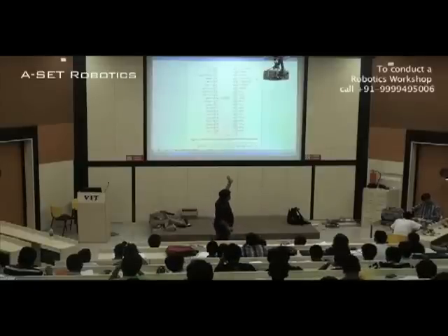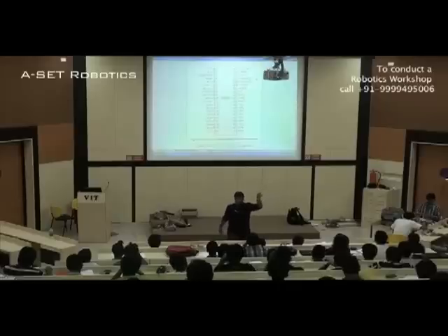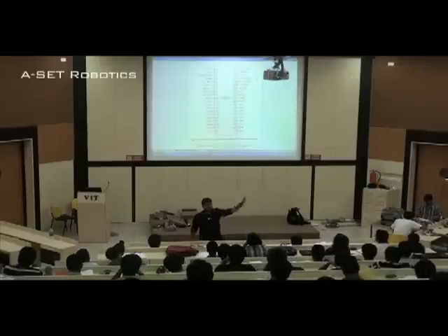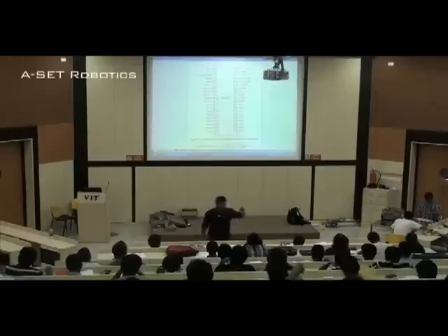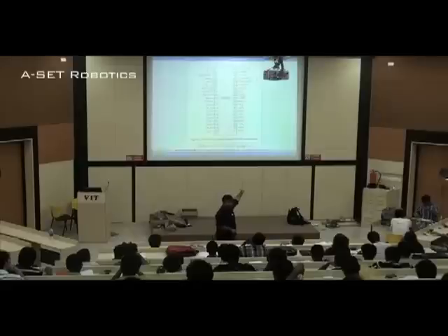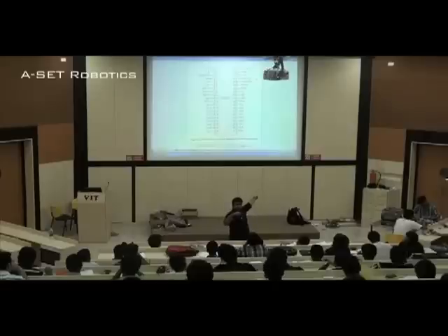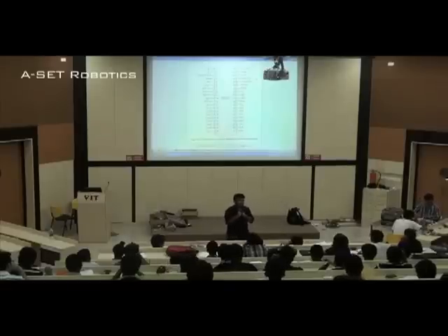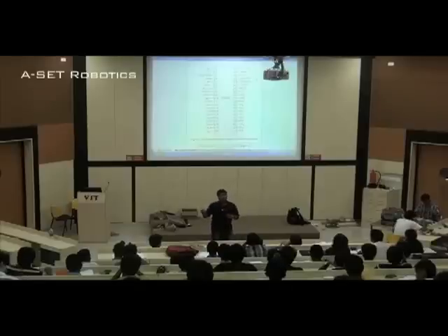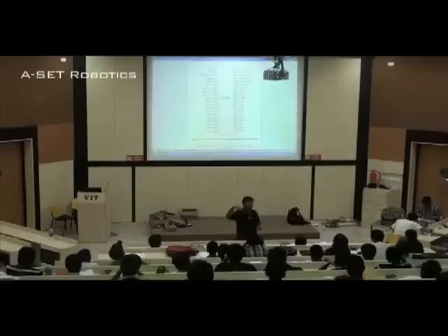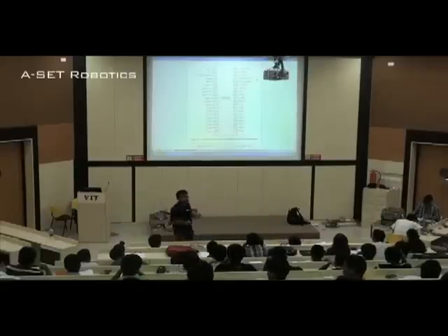So as long as the signal at reset in is 1, the microprocessor would work perfectly fine. And whenever the signal goes 0, that is the reset button in your computer, which goes to this device, and whenever you press it, a 0 signal goes to reset in, and it restarts from the very beginning. How it restarts, we'll come back to the architecture after 5 minutes, and then I'll tell you how the program counter restarts, how the instruction pointer restarts. We'll be talking about all those things.